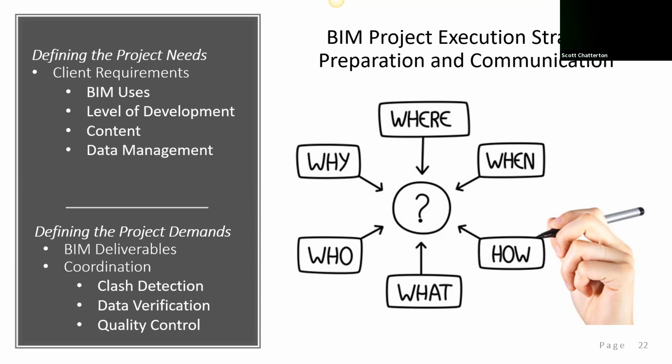So define what the BIM uses are, define what the level of development is, what the LOD, and understanding what impact the selection of LOD has. And the content, making sure you've got clearly identifiable, efficient content is crucial as well. Manage your content. Have somebody take the lead on your content management and make sure the content is clean, efficient and effective, and consistent throughout the whole organization or all projects.